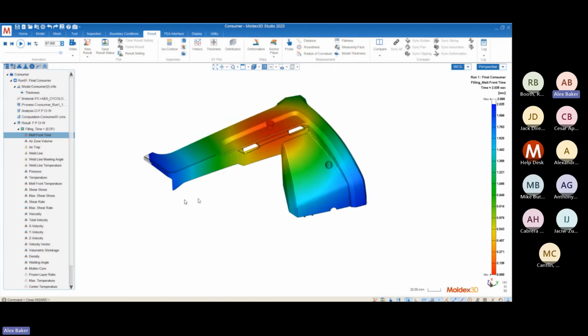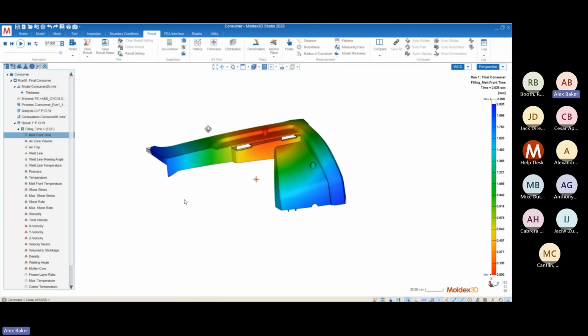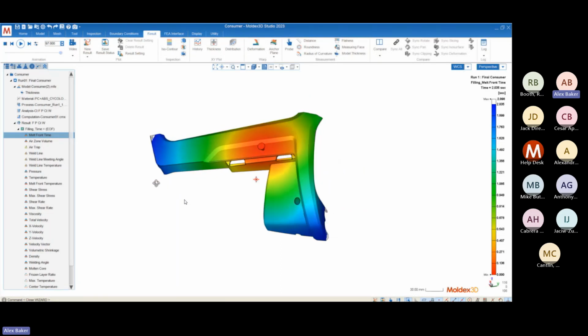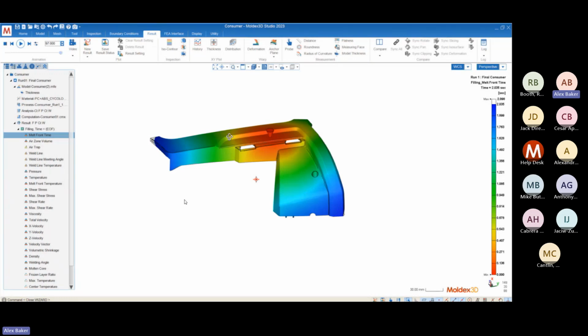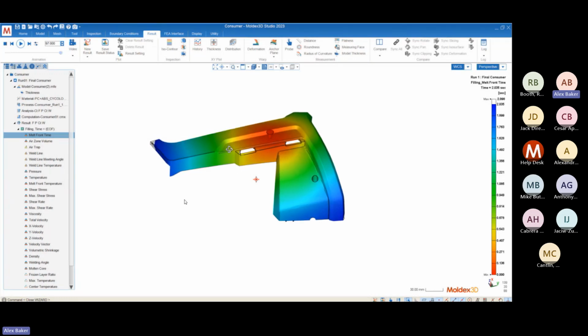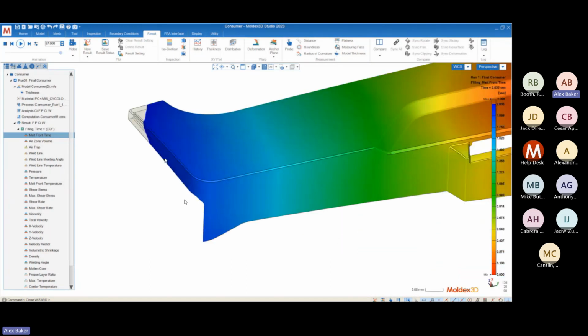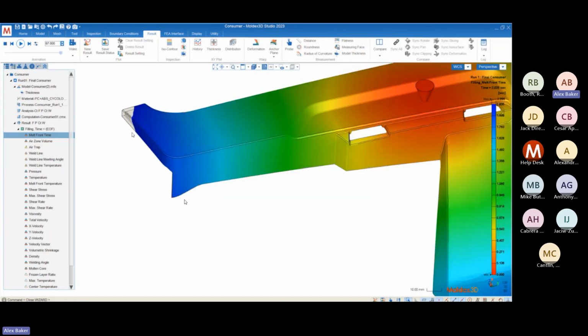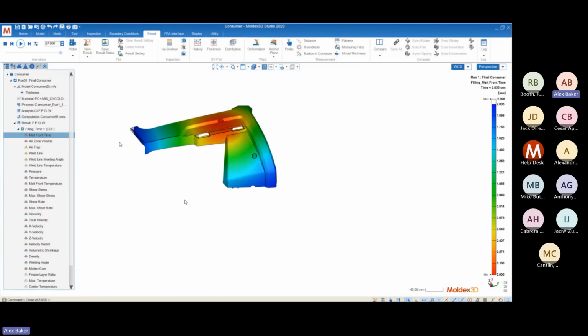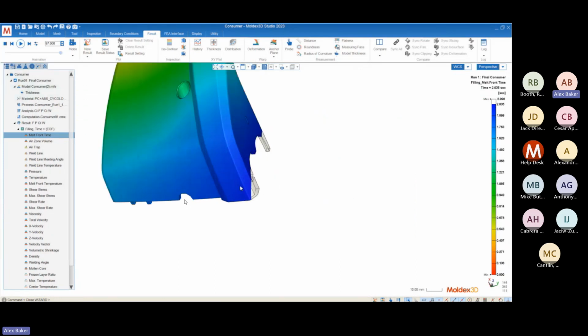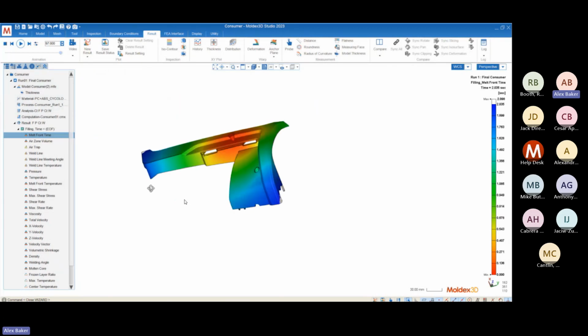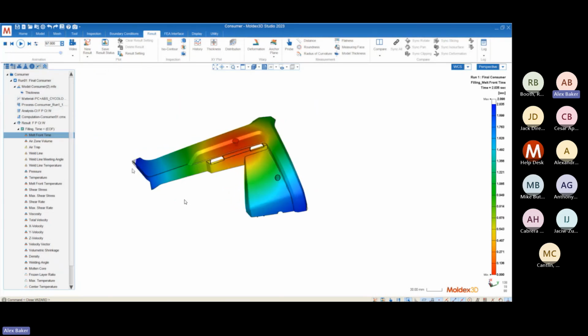There's a couple of reasons that we like to study flow balance. The first of which is going to be based on the pressure required to fill the part. I could avoid needing to look at flow balance if I just put my gate over on this side of my part, because the material has no choice but to flow in one direction until it hits the end of fill over here. But that means that our overall flow length is much longer.